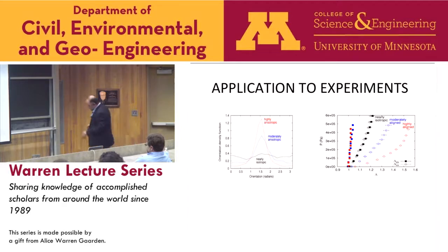Now, the other thing that is interesting is the following. As you can imagine, these fibers are produced at a very high temperature, right? And when the machine spits them, they're basically liquid, right? The speed produces tension, right? And this tension is part of the processing, right? And high tension probably will produce higher crystallinity simply because it straightens, right? And so it's important to recognize that. And what we did, we tried to tell this story, right, in terms of simulations.